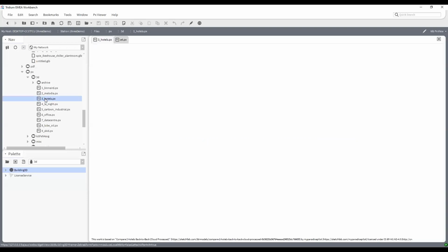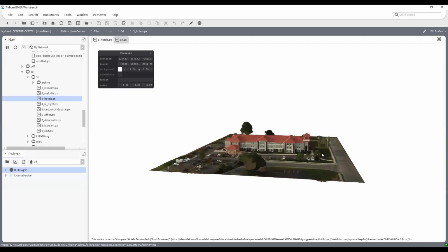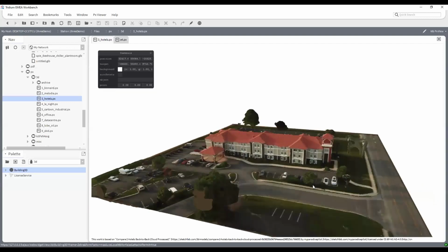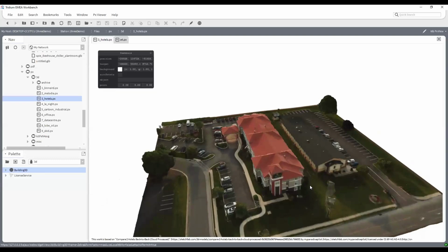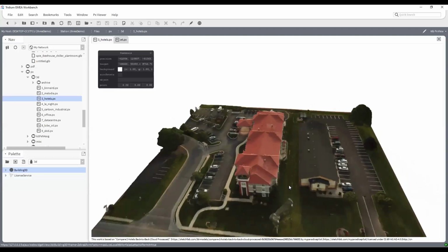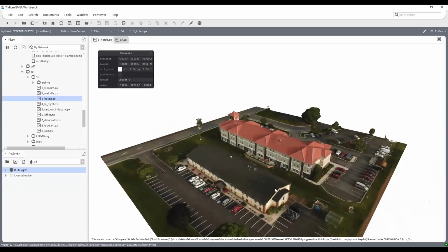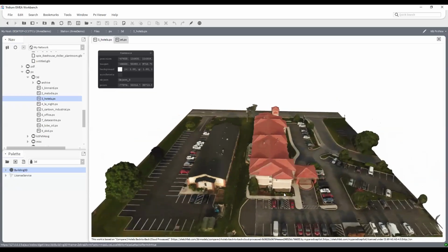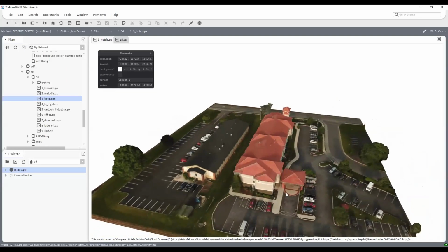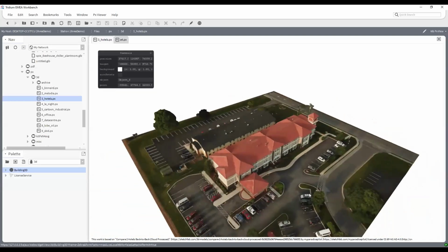Photogrammetry is when you have a drone, and the drone just flies around some building and makes a lot of photographs. Then these photographs are fed into special software, and the software creates a so-called point cloud. Out of the point cloud, it creates a mesh of surfaces, 3D objects, and then it applies textures on these 3D objects. And that's an example of that. So the result could be quite good, especially if viewed from a distance.